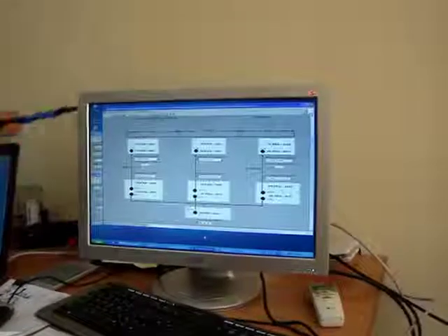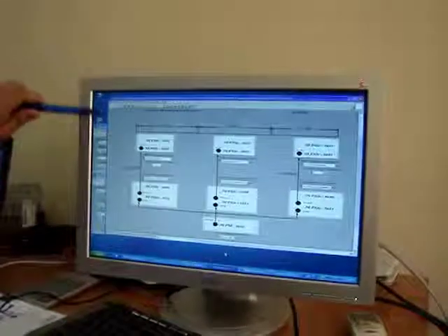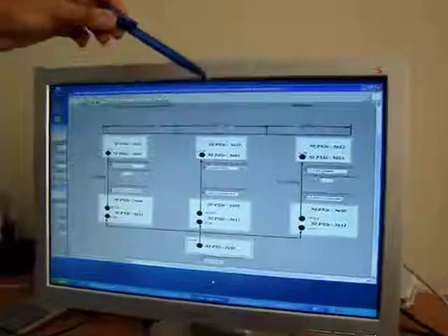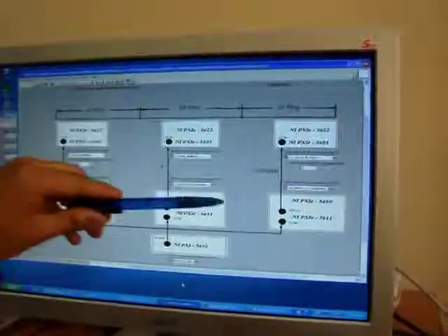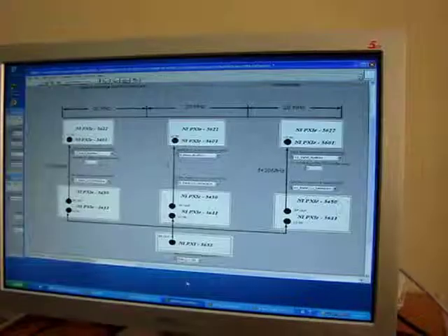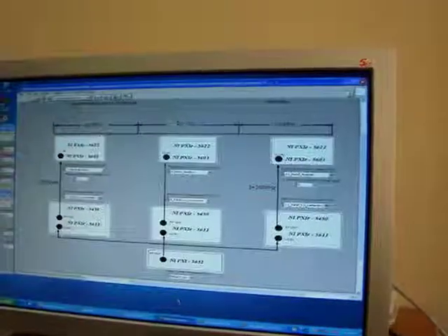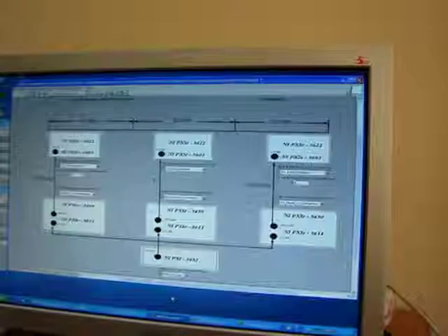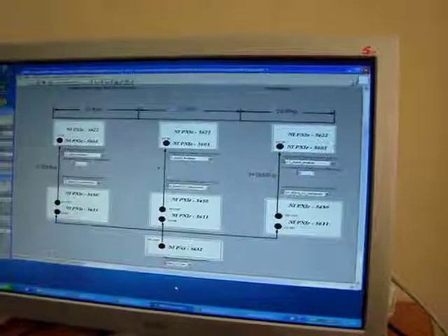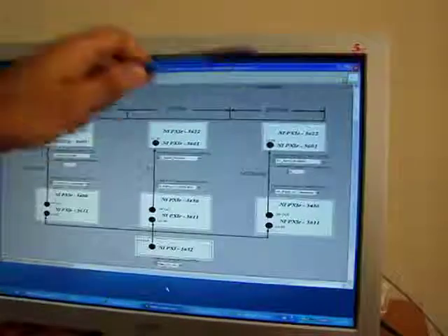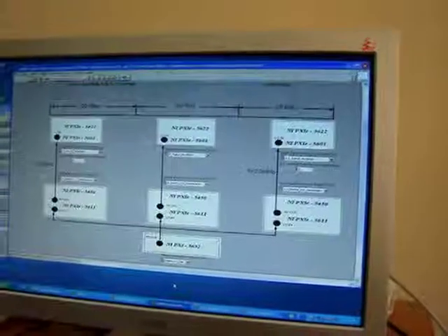For a 60 MHz bandwidth RF record, we must use 3 synchronized vector signal analyzers with synchronized external LOs. Each one acquires the IQ data with 20 MHz bandwidth, and after acquisition these neighboring bandwidths are concatenated via the software to one 60 MHz bandwidth.